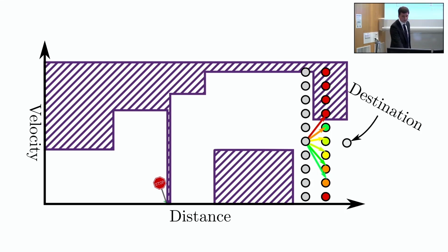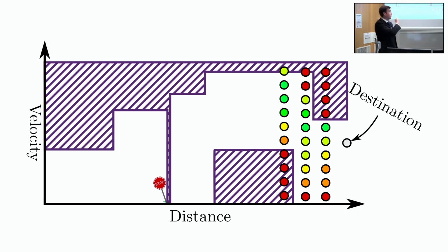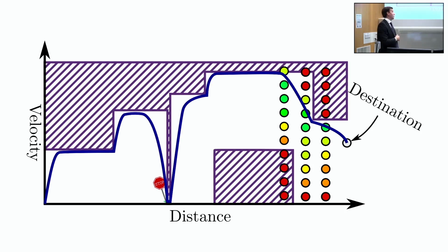And so again, we can simulate all the inputs, add the cost of the state plus the cost of the input, and figure out what the cost is. And it would look something like this. Have as much energy available as possible, unless you have too much available, and then you can't brake. And now we can work backwards, filling in this plot until we get to the start. And then we get the sort of route we want to drive along. So we work backwards, we fill in the grid, we follow, and then we can figure out what route we should take through the grid.